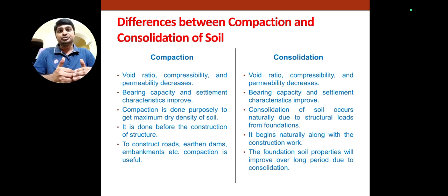Compaction is done purposely to get the maximum dry density of the soil, whereas consolidation of the soil occurs naturally due to structural loads from the foundations. Compaction is done before the construction of the structure, whereas consolidation begins naturally along with the construction work.